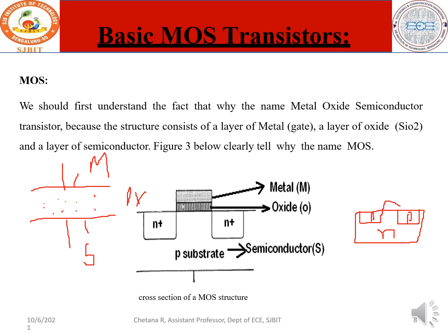Above this you have your oxide. Above this you have your gate. So this forms your PMOS device. So this is how an NMOS and a PMOS device is differentiated. This is your NMOS, which is constructed on a P substrate. This is your PMOS, which is constructed on an N substrate. So you have PMOS, P diffusion, and when you look into this, these three, P, N, P, they form a junction. They form a transistor. So this is how a MOS transistor works.